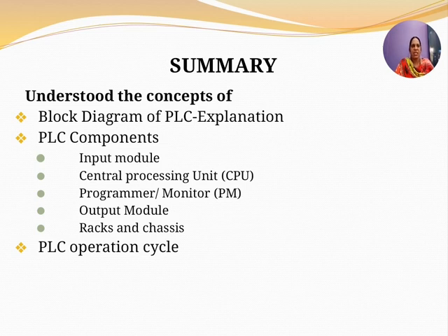So the rack and the chassis: the rack is the important module which acts as a backbone to the system. It holds the PLC. PLCs are available in different sizes and shapes. When more complex control systems are involved, it requires larger PLC racks. Small size PLCs are equipped with a fixed IO pin configuration. So they have gone for modular type rack PLCs, which accept different types of input output modules with sliding and fit in concept. So the input output module will be residing inside the rack or the chassis.